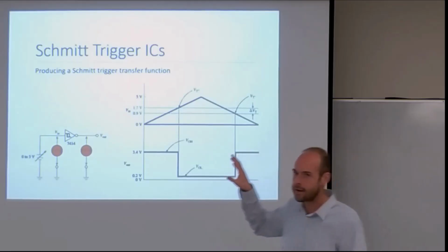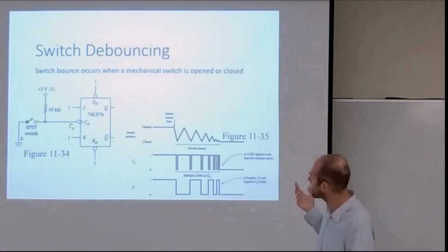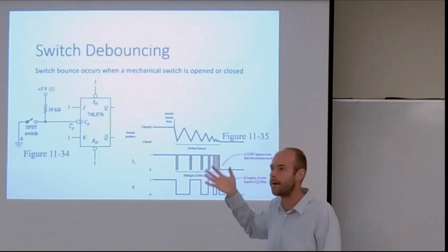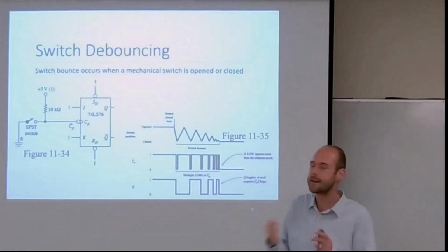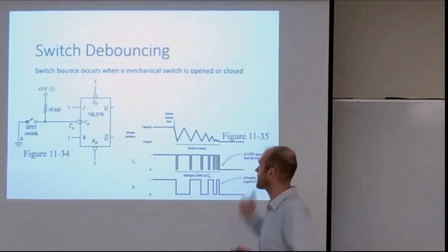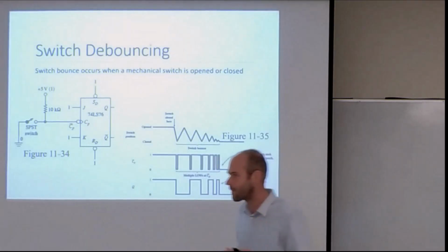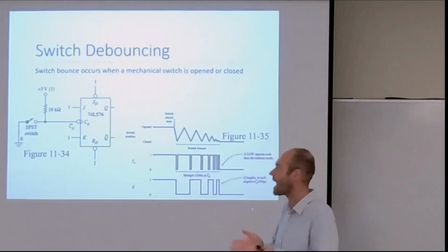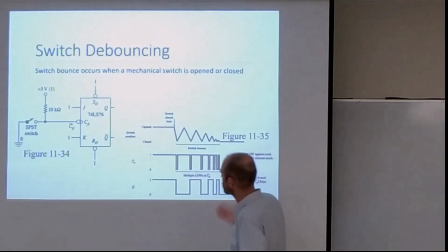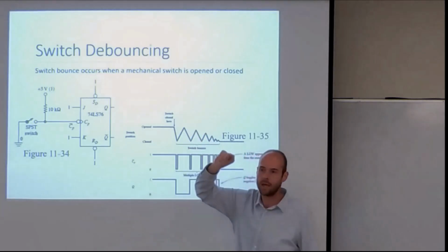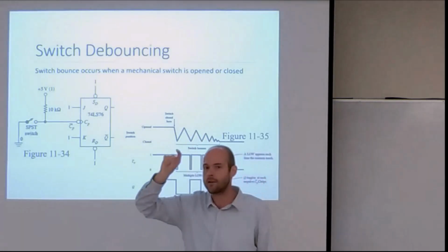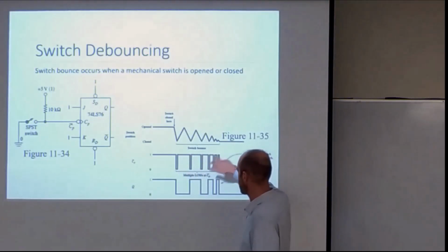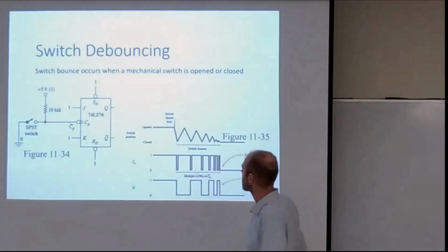So that's just one of a few items we're going to talk about. We're going to highlight again the idea of switch bouncing. We've talked about this in previous courses in a few different ways. Essentially, a switch is a mechanical device that has potentially some spring constant as contacts collide. At that collision point, you can have bouncing between contacts, and electrically, that's going to look like a switch bouncing open and closed. And so you can see those bounces happening here.